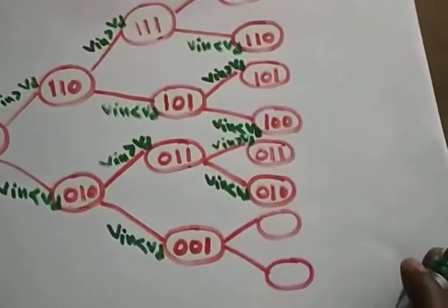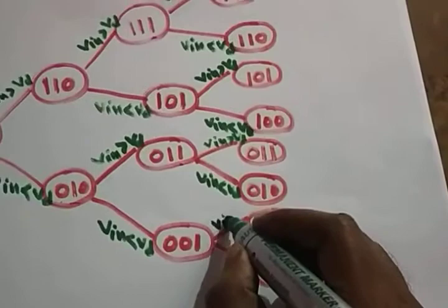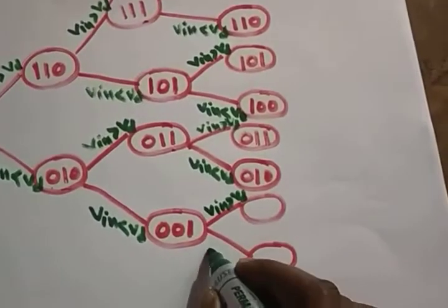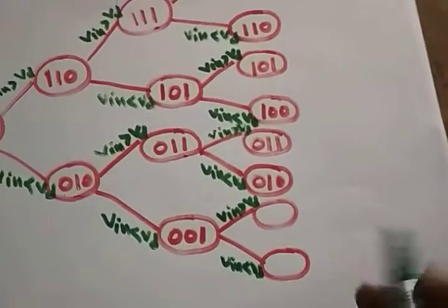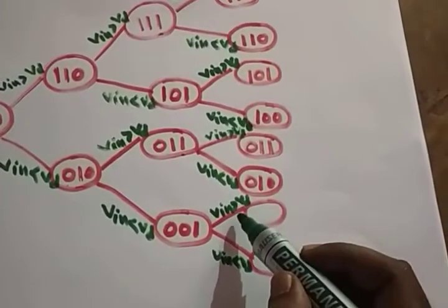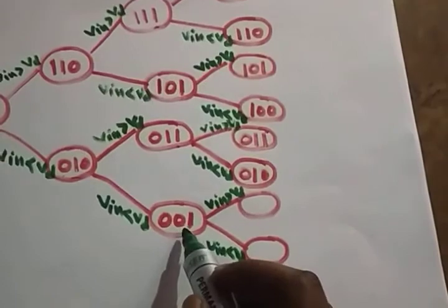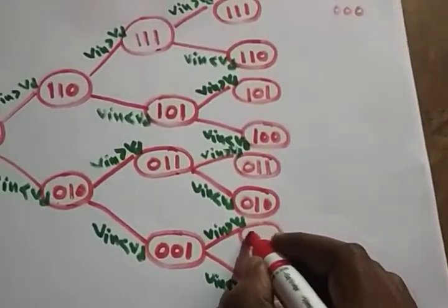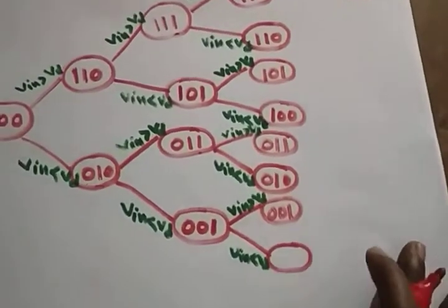Simple, it's an algorithm approach. If you know the algorithm, the working is very easy. Vin greater than Vd, Vin less than Vd. If Vin is greater than Vd, the next bit you are going to set to 1. Is there any bit to set? No. You just leave it as it is. There is no bit to set.